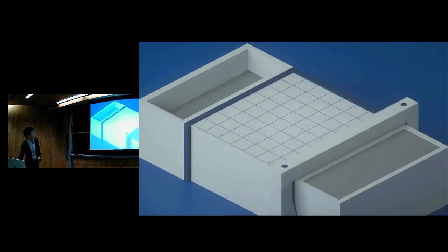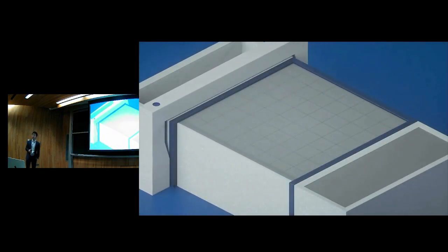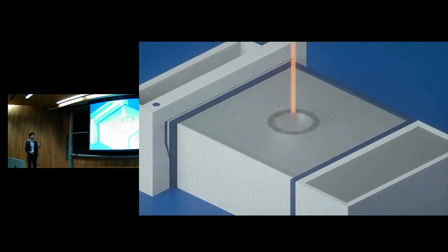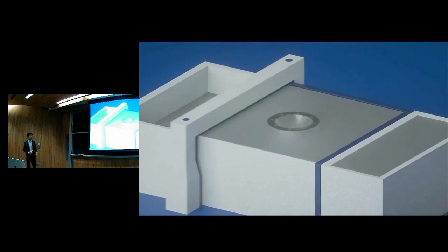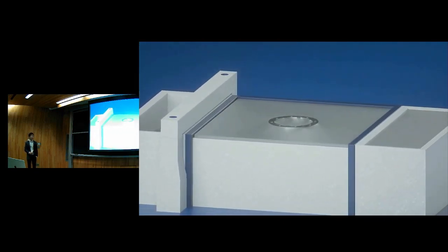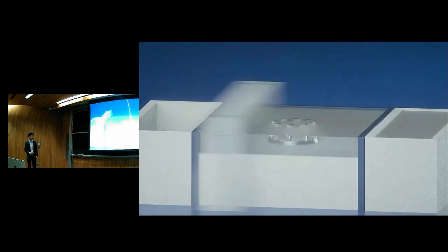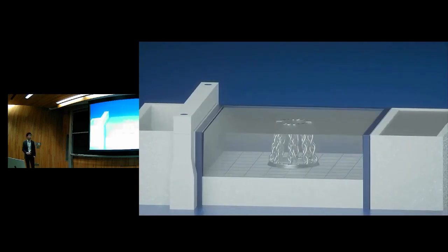So what is additive manufacturing? As some of you may know, metal additive manufacturing, such as laser powder bed fusion or directed energy deposition, is a type of manufacturing method that utilizes a high energy density laser to melt and sinter metallic powders in a layer by layer fashion to produce 3-dimensional structures.